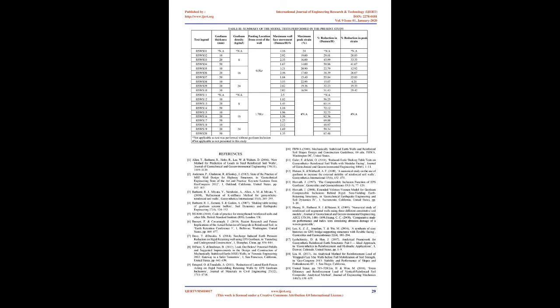Fig. 7. When geofoam is placed behind the reinforced zone, the reinforced soil mass is allowed to move towards the backfill, which causes the frictional bond development between the geogrid and the surrounding soil. Due to this, the wall face movements get reduced for an identical settlement of the footing in geofoam inclusion cases than that of the without geofoam case.